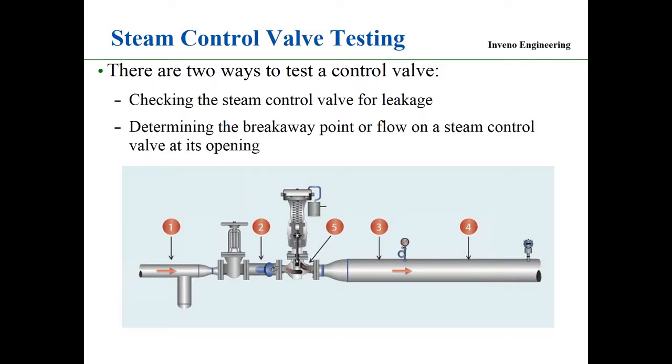Well, the thing about it is that that's a common problem, but what we do is penetrate the insulation with a small hole we call test plug. So you make an opening in the insulation so the probe can go in and make contact with the line. Once the test is done, then we plug that hole with a plug we call test port plug.